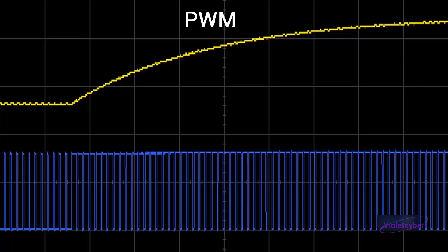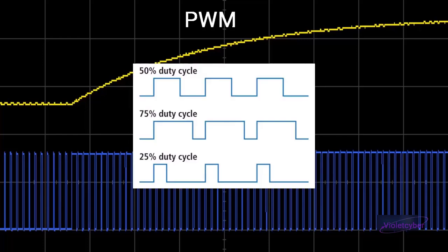So, as was said, a PWM signal stays on for a certain time and will be off for the rest of the time. If we put the signal in the one state all the time, that is, there is no time for 0, then it can be said that the PWM pulse remains on for that whole time and is at 100% duty cycle. So if this is applied to a motor, the motor starts rotating with its maximum power. And for example, if the robot moves with this motor, it moves forward at its top speed. Also, the PWM duty cycle is called duty cycle.